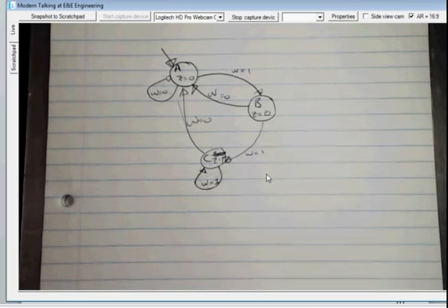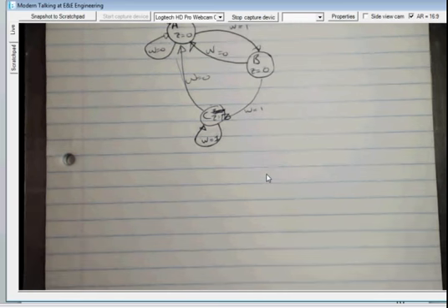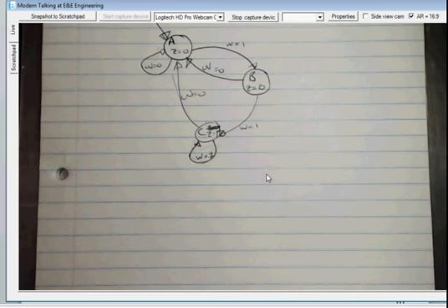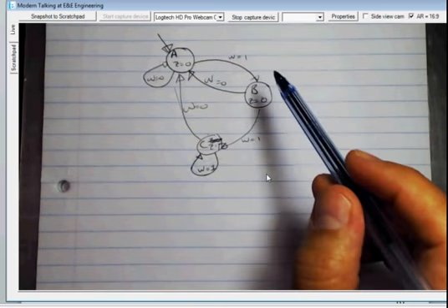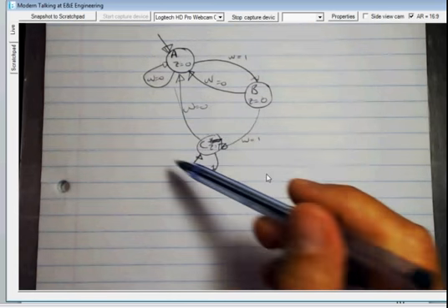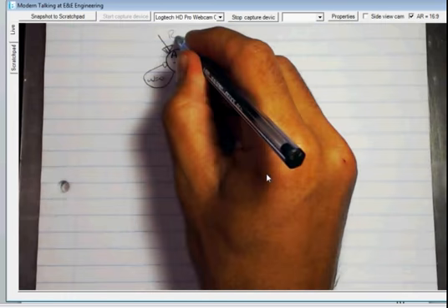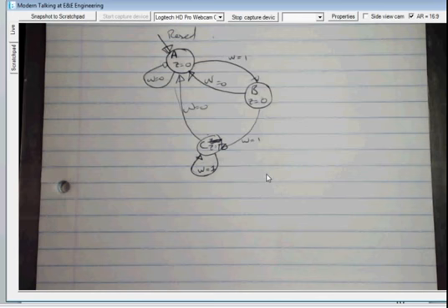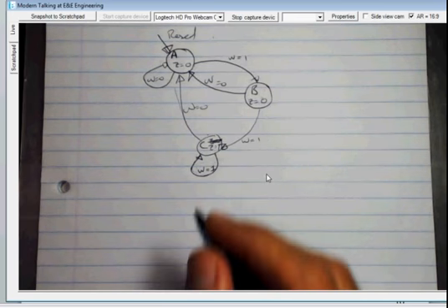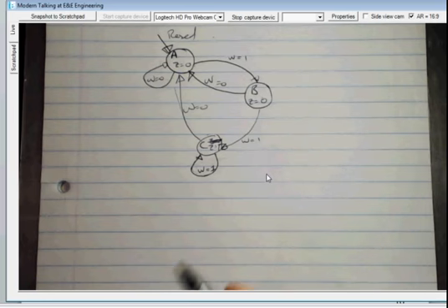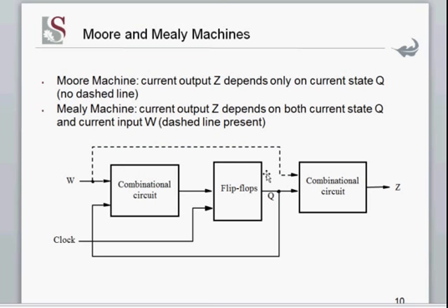Okay, so that brings me to the next step in this design sequence, and I can guarantee that this will be the difficult part. This state machine that we've just done, that's the difficult part. When you've done that, the rest is really fairly easy. All we need to do now is make a state table, and before that I just want to explain what we're doing yet again, just so that you get the bigger picture. The bigger picture is we want to design the logic that performs this function, and we want to put in flip-flops to remember the state.